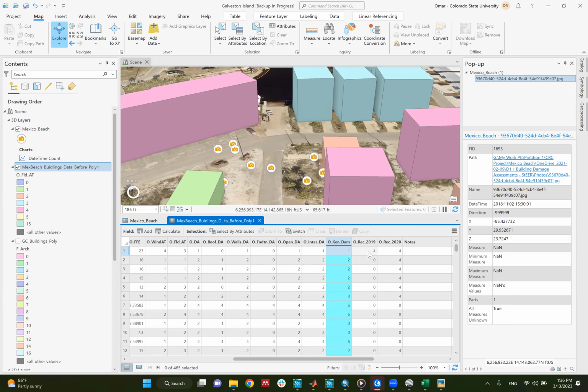The thing is, my damage assessment will be completely different from your damage assessment. You will see the damage from different sides. We all have the same sheet that describes the damage. Damage state 1 should be a certain level of damage for the roof, a certain level of damage to the windows, the doors. But when every one of us does this damage assessment, maybe you give this building damage state 2, and I give this building damage state 3. Not only from the pictures: if we both are in the field and we bring the same team to do this damage assessment, definitely another team may have a different damage assessment.